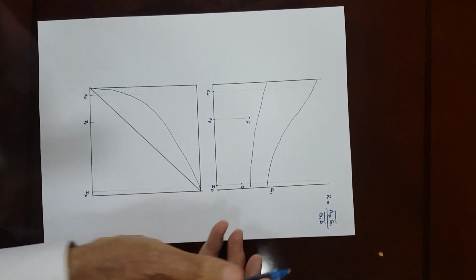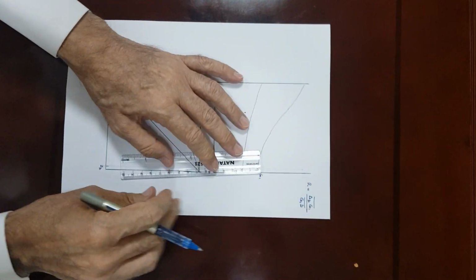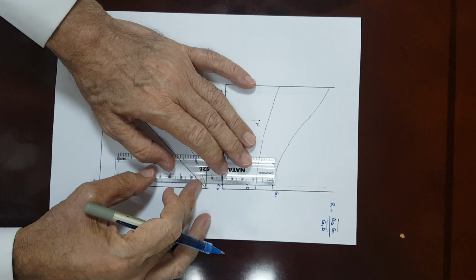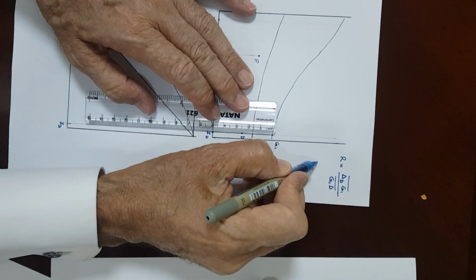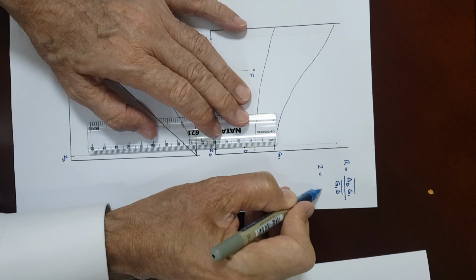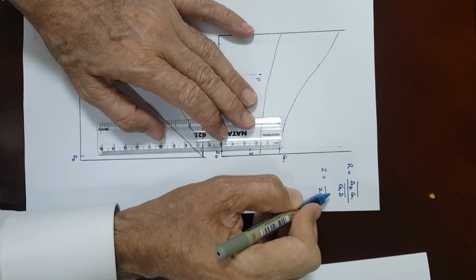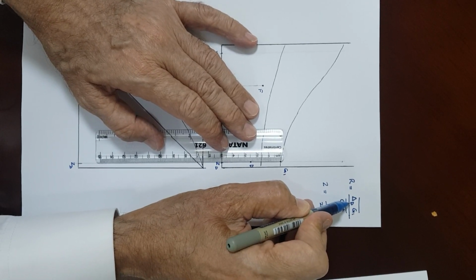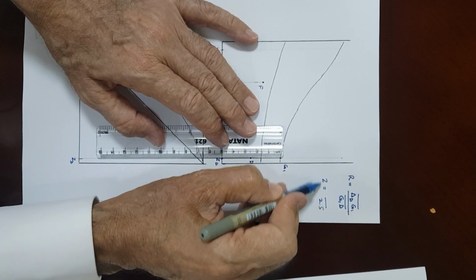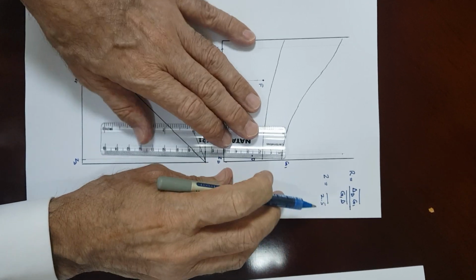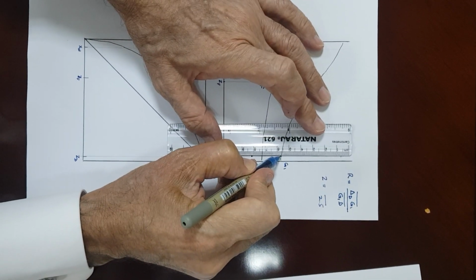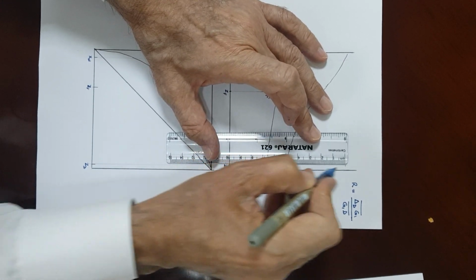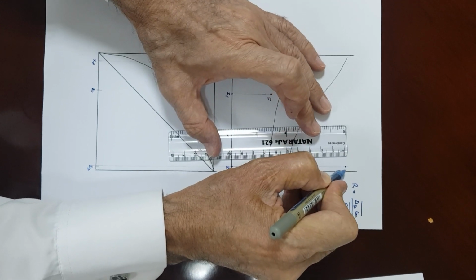So we can do it graphically here. We measure it, and that's 2.5 centimeters. Let's assume a reflux ratio of 2. That can be used to find the length of the line delta D to G1, which should give us a length of 5 centimeters. So we measure from G1 a distance of 5 centimeters, and that gives you your delta D.